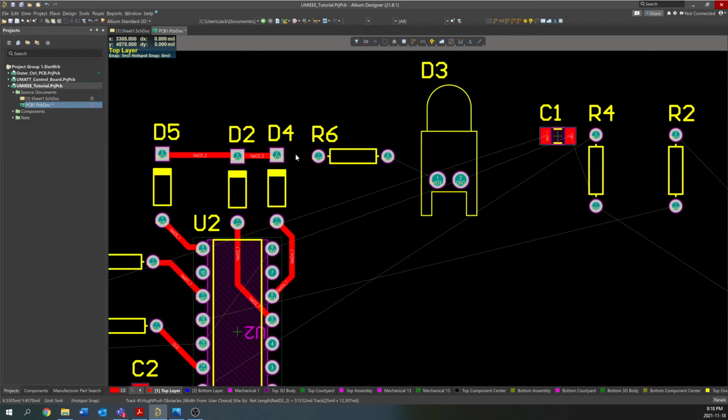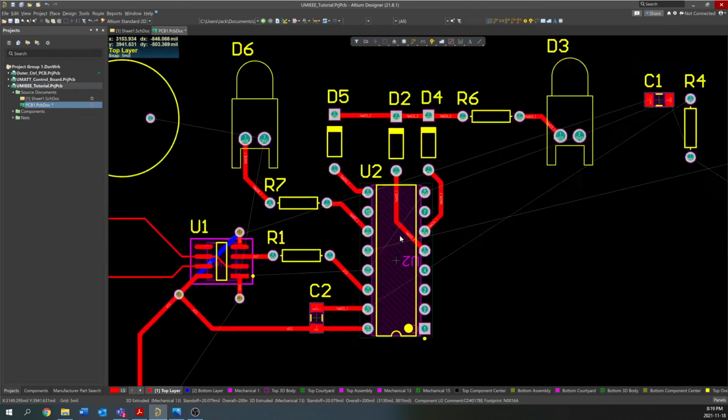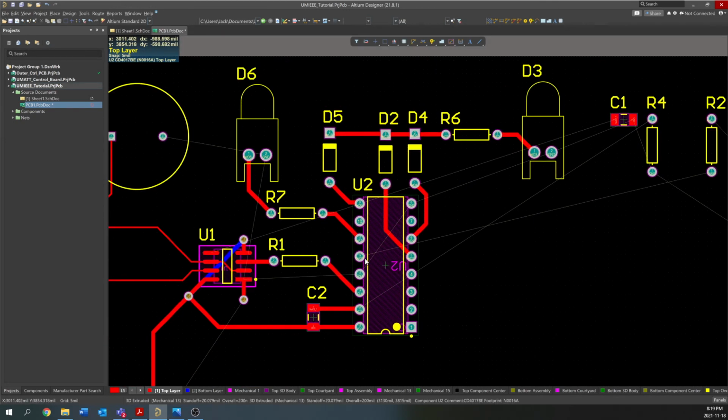So you can see that I'm kind of laying the components out as I go. But what I do personally a lot of the time is picking the components that have the largest number of pins or pads ahead of time and designing your layout around those components. That's generally the best way to go, in my opinion, because you'll find that those components with a high number of pins end up driving how you lay out your design, because that's what everything connects to.